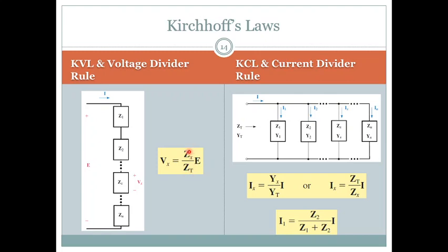All these four figures are in the complex number domain. So instead of resistances we have impedances, and all the parameters are with a magnitude and a phase angle now, right? That's the main difference from DC to AC. Other than that, you just follow the same procedures.